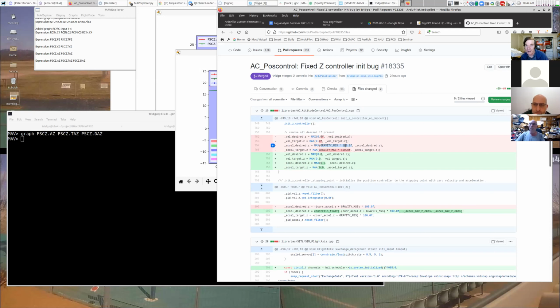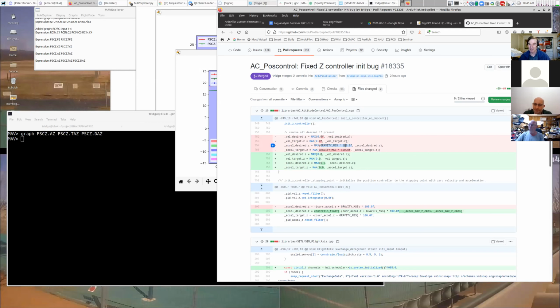And this bug was entirely reproducible in the simulator. We've got a nice little simulator of this exact aircraft, and it also reproduced these 400-foot climbs after transition at high speed. I had not chased it down when I was initially developing it, excited to get the model out there. Once I put this fix in, instead of going up by 100 meters on a transition, it goes up by about 7 meters, which is much more reasonable. So the aircraft does not climb like crazy when we transition to vertical flight.